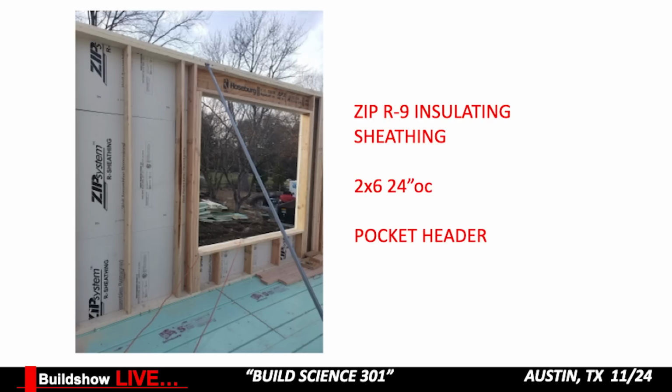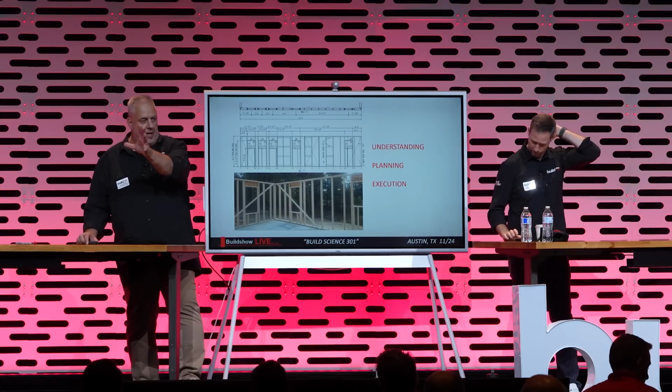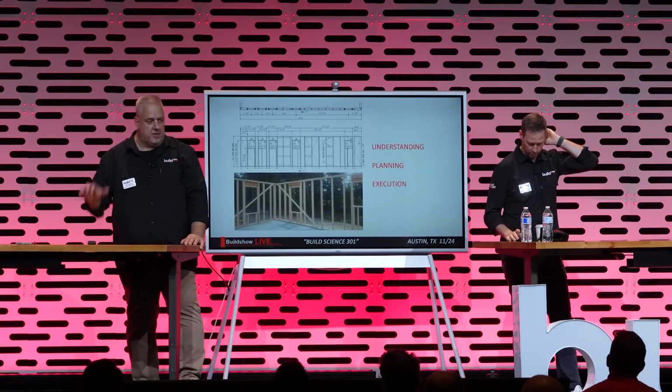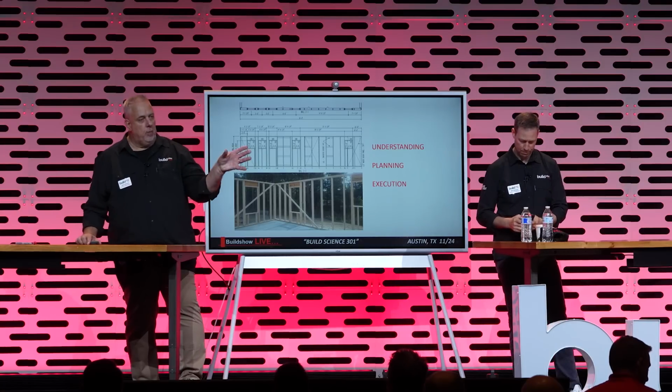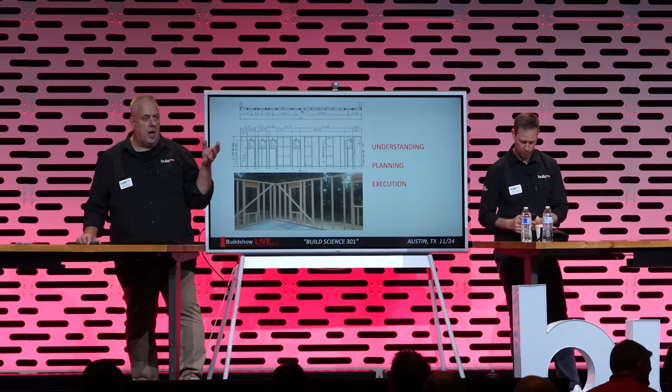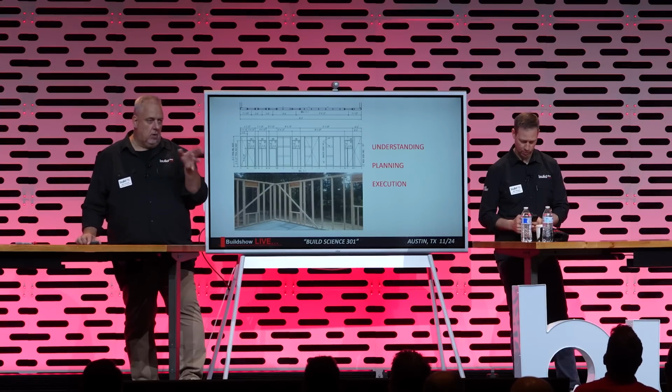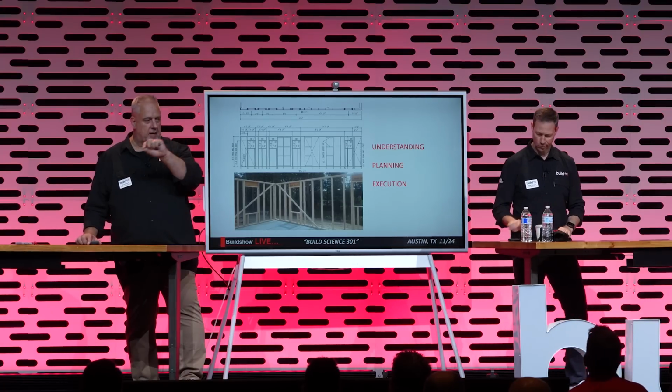But in this case here, you can see that's a 2-ply LVL, about a 7-foot opening, and we still have insulation. But when you talk about executable, think about this detail. The insulator does what the insulator does when the insulator does it. When we do a set of drawings, we actually have a header schedule. Probably has 25 different headers, A, B, C, D, all the way to J or K, L, whatever. And then when we do our framing plans, and we usually draw, most of the time, we draw our framing plans, not all the time, and then we just send them out for the engineer to mark up. But at every opening, it'll say header A, B, C, or D.